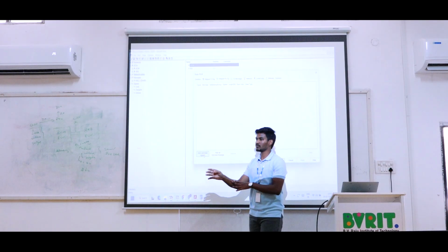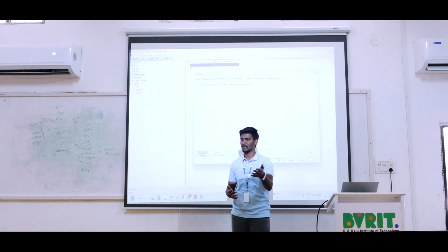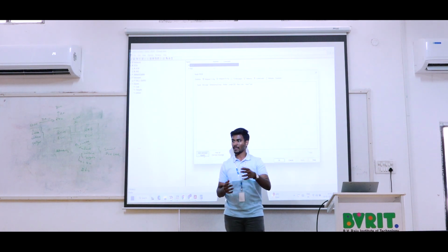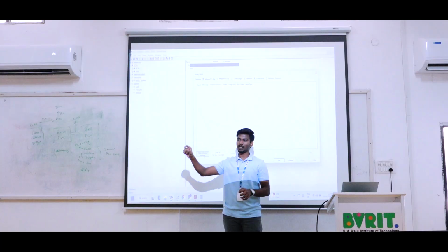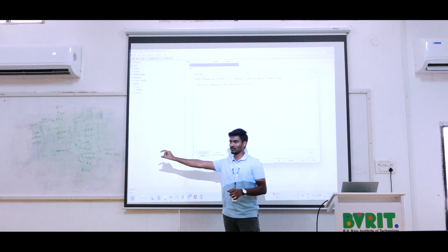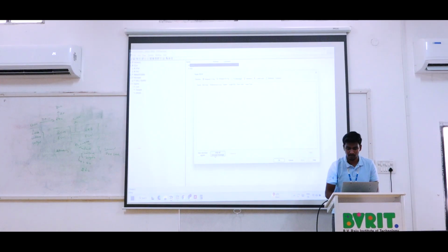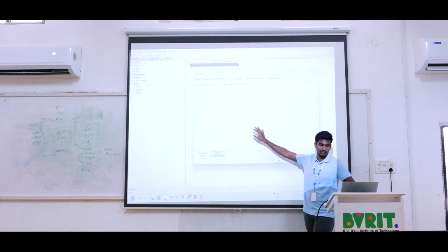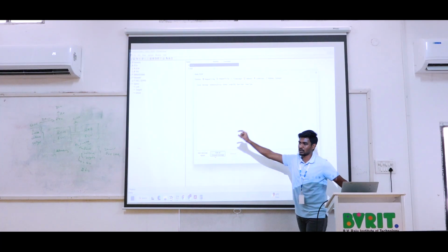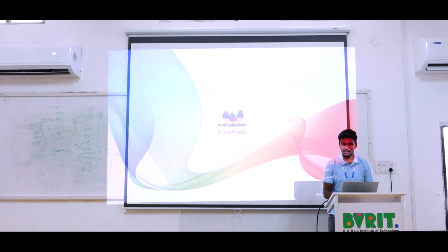But sometimes the transmission control sends values like gear shift values, vehicle speed values, some shaft values. But in our instrument cluster, we need only the vehicle speed value. So at that time you pick particular signals only. That is what is mentioned here: add individual signals, or add all from one message. If you are accessing all signals from a message, you can give this. Else, if I want only a particular signal, we can give add individual signals.